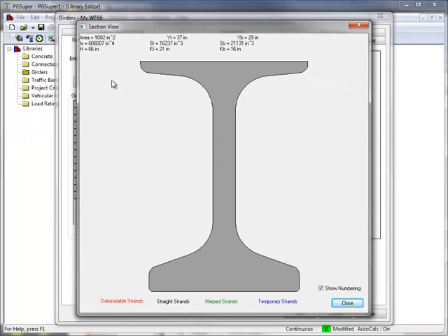As I mentioned earlier, our goal is to match the CalTrans shape. This not only means the shape geometry, but also the section properties, such as area, moment of inertia, and CG locations. For some cases, you'll find that the section properties don't match exactly, even if you get the geometry perfect. PGSuper computes the properties exactly for the input shape. However, oftentimes the engineer who first developed the shape made approximations when computing the properties. For instance, items like fillets and chamfers may have been ignored during the initial shape development. This can be a problem for some sections, and you may find that the properties don't match as well as you want. So you may end up having to tweak the shape a bit to get the section properties to match. I'm typically satisfied if I can get all structural properties to match within 1%.